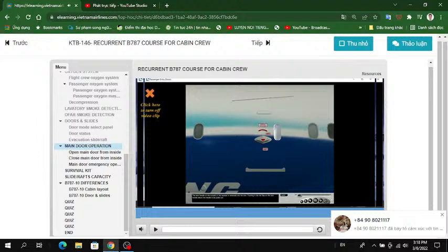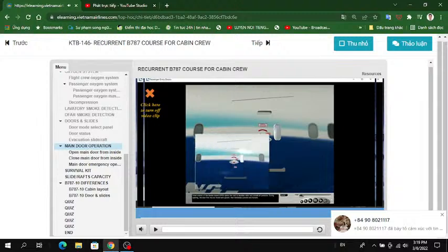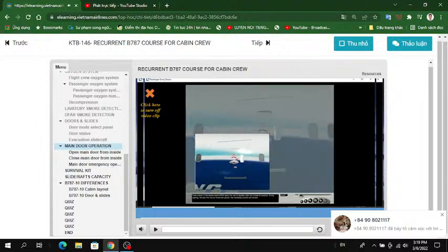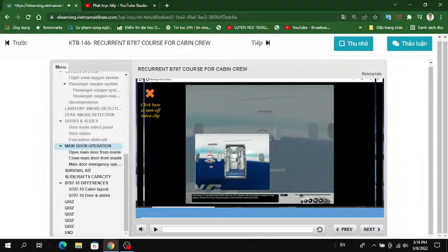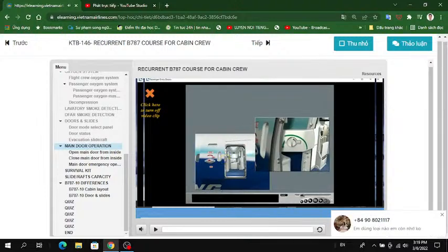Pushing in the red flap on the door handle allows the handle to be pulled out. Rotating the handle in the direction of the arrow then unlocks and unlatches the door. Initial rotation of the handle toward open opens the vent to equalize cabin and outside air pressure. During opening, the door first moves inward and upward, then translates outward and forward. Each door is held in the open position by a gust lock. It also prevents the door from movement due to wind or unusual attitude.